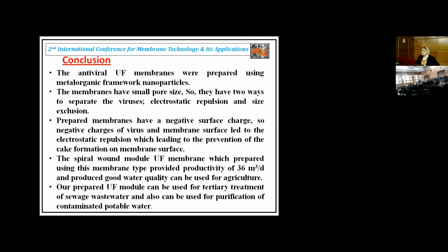Conclusion: the antiviral membranes were prepared using metallo-organic phenol particles. The membranes have small pore size, so they have 2 ways to separate the viruses: electrostatic function and size exclusion. Prepared membranes have a negative surface charge, so they can separate viruses with a negative protein charge, which leads to the prevention of cake formation on the membrane surface.